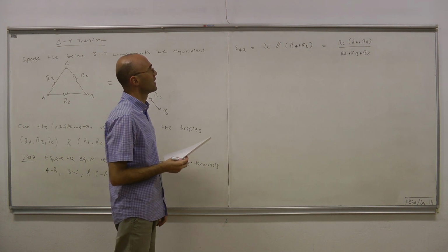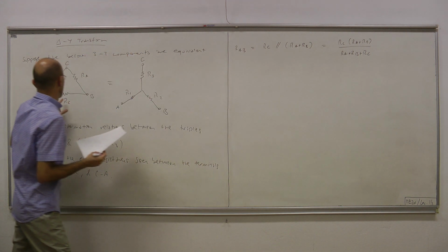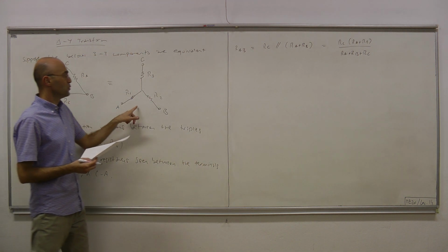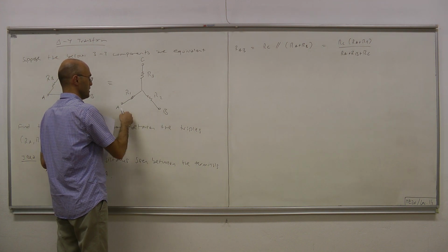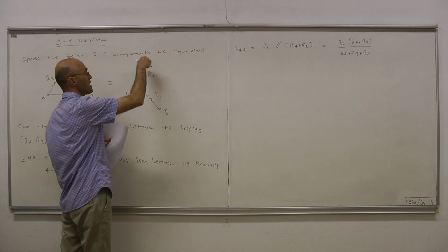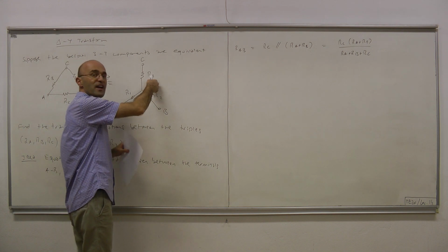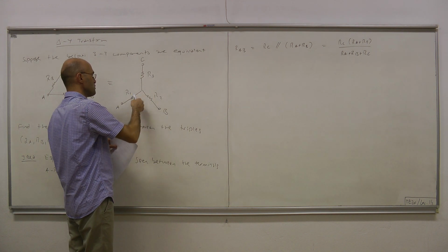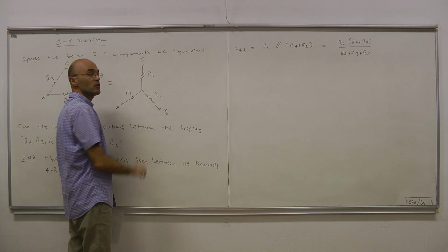So that's what I read for this one. And if I do the same procedure here, the input resistance seen from the terminals A and B is R1 plus R2. Since nothing is connected to the terminal C while making the measurement, this R3 has no effect whatsoever. In other words, R1 and R2 become series because there is no current escaping to R3.